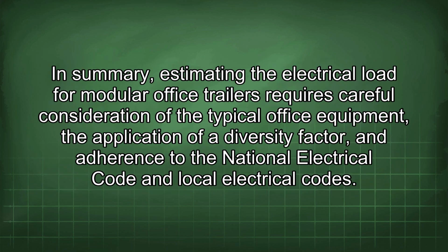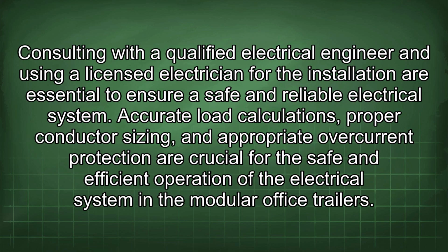conditions. In summary, estimating the electrical load for modular office trailers requires careful consideration of the typical office equipment, the application of a diversity factor, and adherence to the National Electrical Code and local electrical codes. Consulting with a qualified electrical engineer and using a licensed electrician for the installation are essential to ensure a safe and reliable electrical system. Accurate load calculations, proper conductor sizing, and appropriate overcurrent protection are crucial for the safe and efficient operation of the electrical system in the modular office trailers.